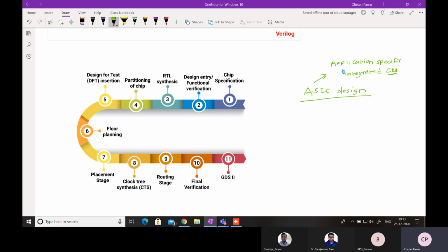If you talk about the FPGA, you write a code in VHDL or Verilog language and put it into the FPGA. By programming, you can use an FPGA like an encoder, or like a digital to analog converter. For any kind of application you can change its functionality. But application specific integrated circuit means, for example, a video processor chip in your cell phone.